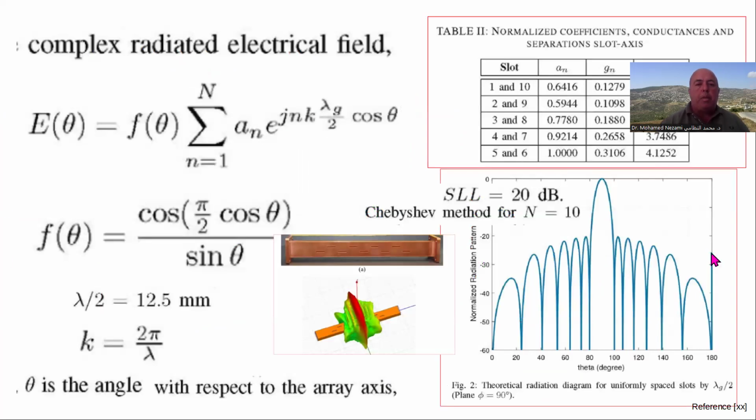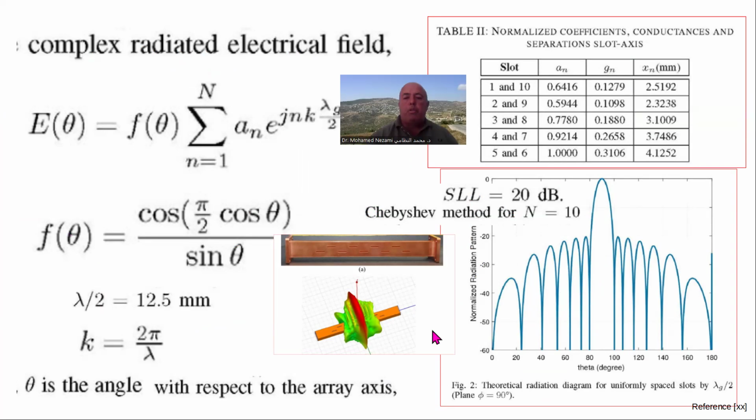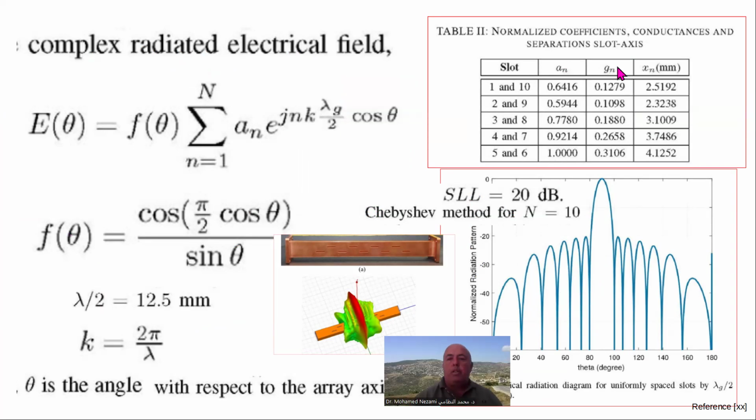And here is an example that I put in here, which I will show in the coming session. I took this and laid out the equation, a half-wave dipole in here, and then some parameters in here, and these are the tapering coefficients here, and the GNs, and of course the XNs. So these are related, okay? And this is the hardest part of designing these.